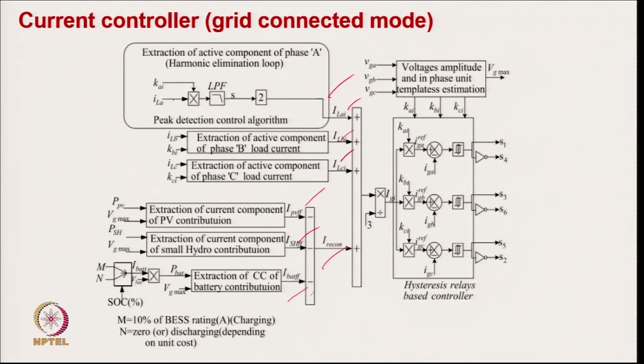So, that gives us the net here, typically the weight, and you have the load, typically all three load currents, which we really get from here and divide by averaging for all three phases. And we have a typical amplitude of the grid current, we have a phase here, and then we have a reference grid current, and we compare with the sensed grid current and give the gating signal.